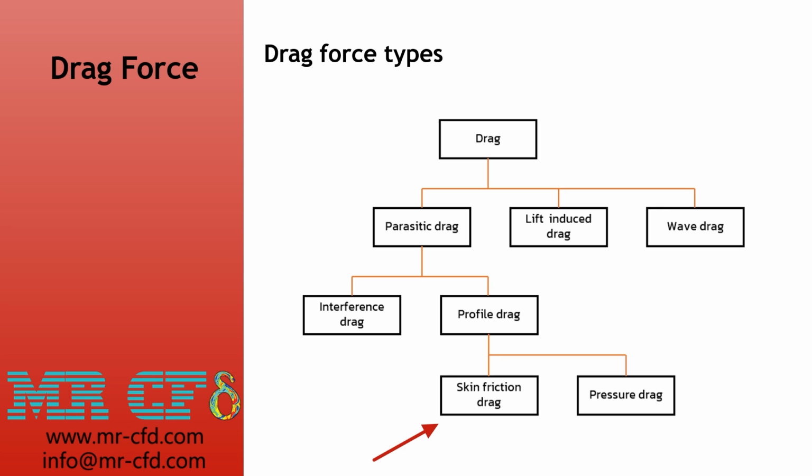For example, for skin friction drag, we can apply the sense of skin friction drag by changing the roughness of our surface, our wall. But this roughness for the wall is just a constant, and it's not actually modeling the roughness distribution on the wing. For the pressure drag itself, we can see the pressure distribution, but this is just a force and not stream related.